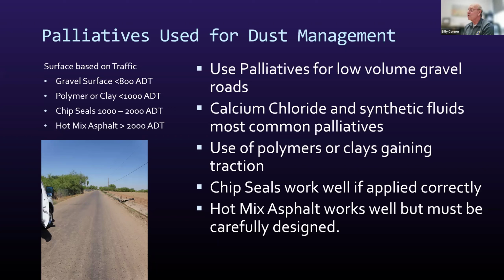Polymers are a little bit problematic because of grading. If you grade it, you have to start over. With clays, the nice thing is, as you grade it, you pretty much treat the surface as you would otherwise, but it does give you a material where the water runs off and very low dust. Chip seals or surface treatments work well if applied correctly.